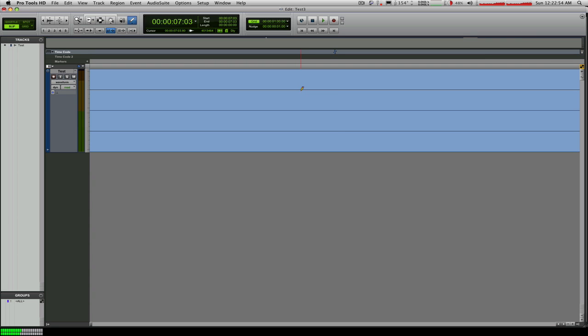And the purpose of this tool is, as you might expect, you can draw with it, and particularly draw in a waveform. I found this pretty interesting tool. I've used it actually in the past for if there was an anomaly like a tick or a pop in a soundtrack here. Maybe you'll be able to hear it if I scrub over. If that had already existed, of course, if I hadn't just created it, you could conceivably go in and draw a line, a zero line at this point, and then hear nothing, obviously. In this case, it's silence anyway.